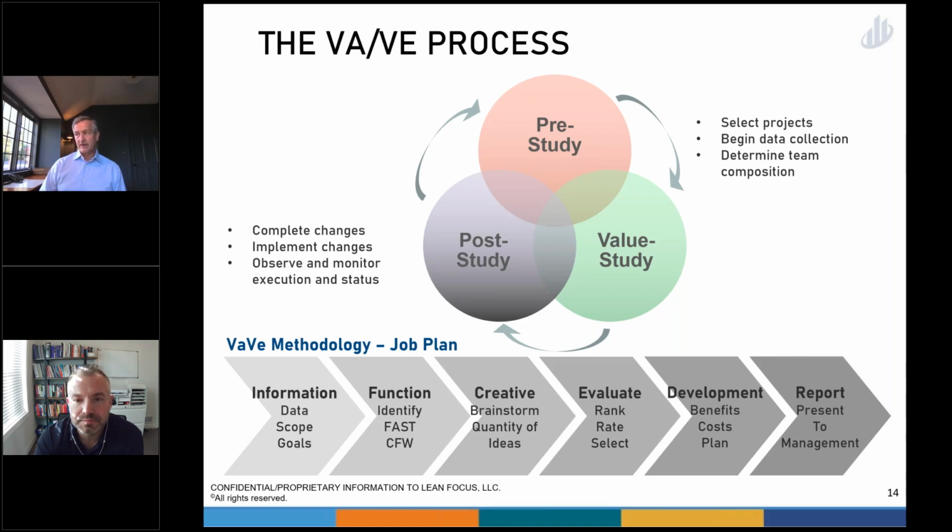It can identify unnecessary, missing, or duplicate functions that you might have. Once you've got the cost of the whole unit spread out over all the components, you start into brainstorming to say, hey, what options or ideas are there here? And we evaluate those and rank them based on how complex they are and what we think the value might be.